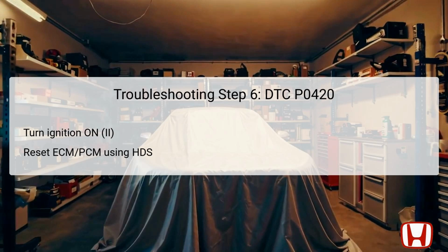Following the reset, the vehicle's management system and sensors adjust their functionality to align with the new component specifications, ensuring better performance and efficiency. Step 7 requires performing the idle learn procedure for the ECM or PCM after the reset. This procedure allows the system to learn the correct idle settings under the new component configuration, ensuring smooth running and optimal engine performance.